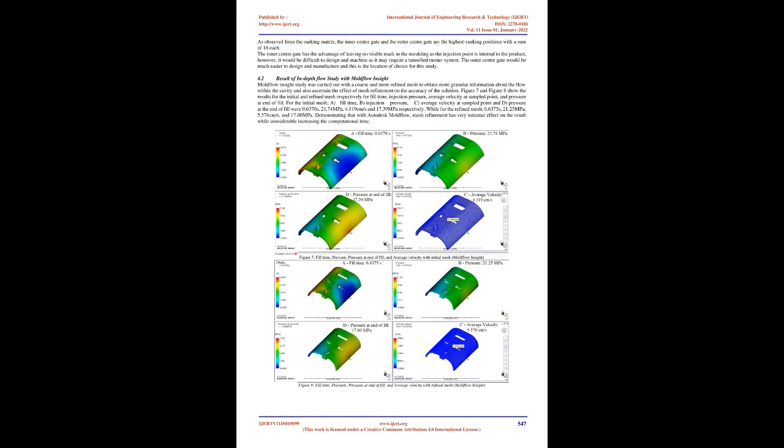The CAD geometry was imported into ANSYS SpaceClaim as shown in Figure 5. Ansys Mechanical was launched to carry out meshing. Within Ansys Mechanical, named selections were created to serve as labels for the boundary conditions in the Fluent solver. These were inlet, wall, flow domain, and outlet. For better results with curved surfaces, the sizing section of the mesh detail was set to capture curvature and proximity. Further sizing settings for the mesh resulted in 192,335 elements.